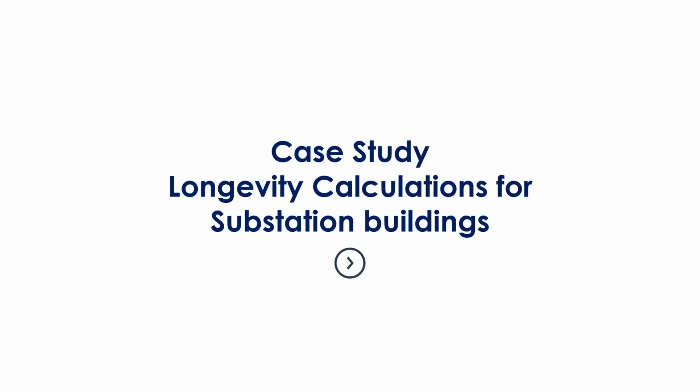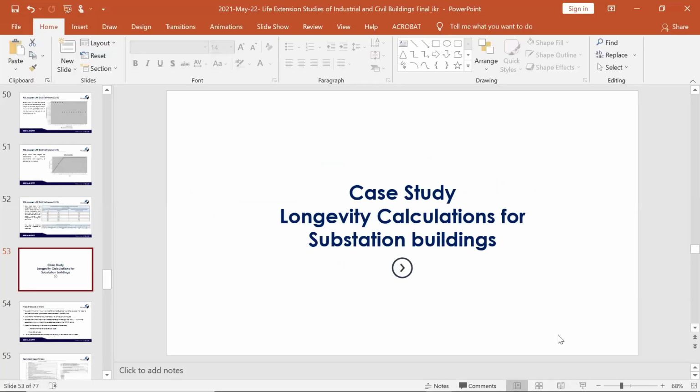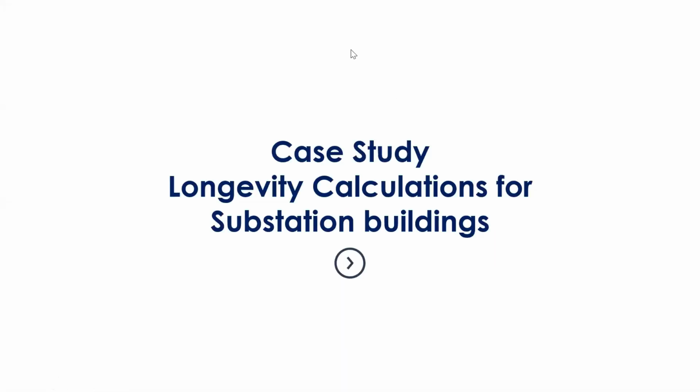Yes. Okay, next question. So in case a third-party structural audit confirms a particular structure is still safe even after completing the service life of 30 years, but as per the design life, the same has to be replaced with a new structure. So in that case, what suggestion can be taken? Is it worth taking the risk to allow the structure to be left untouched, or should they proceed with the design life? No. Design life is not a criteria to demolish the building. Design life is the initial, and there would be a limiting component in the design basis, and the life is extended based on the actual. There are steps, 8 factors, and those all factors are being analyzed, and then the next decision is being made. If we have to go only by a design life, then every building should be demolished after 30 years or so.